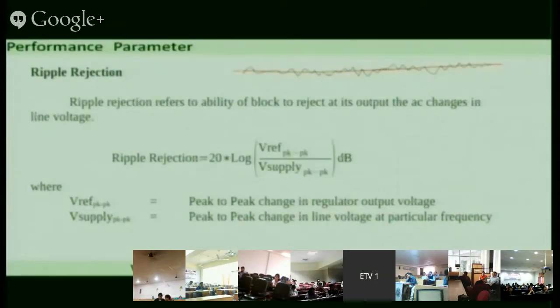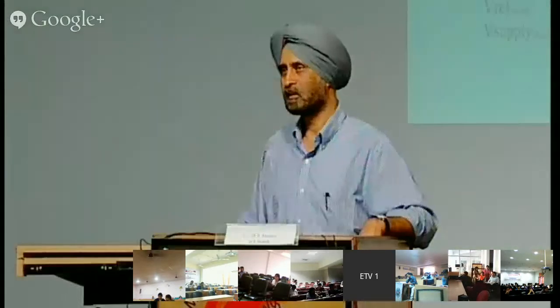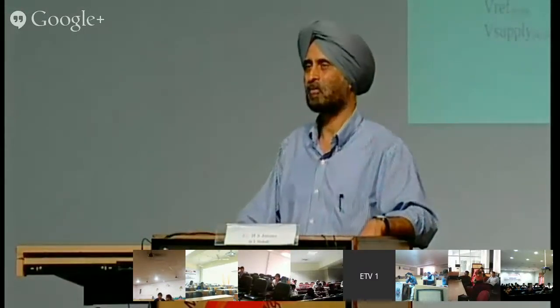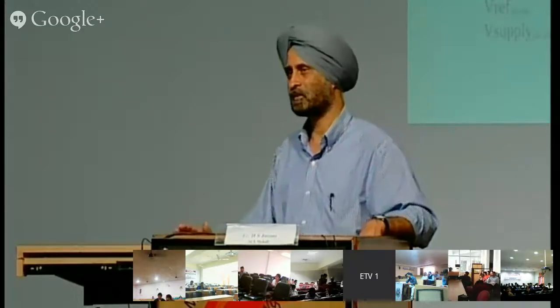If this ripple is more, like here, this is more ripple. If this ripple is more, it may have some side effects, it may destroy the circuitry. So first we have to measure the ripple, and we have to specify a limit that it cannot be more than this. So normally ripple rejection is given in 20 log, in decibels.